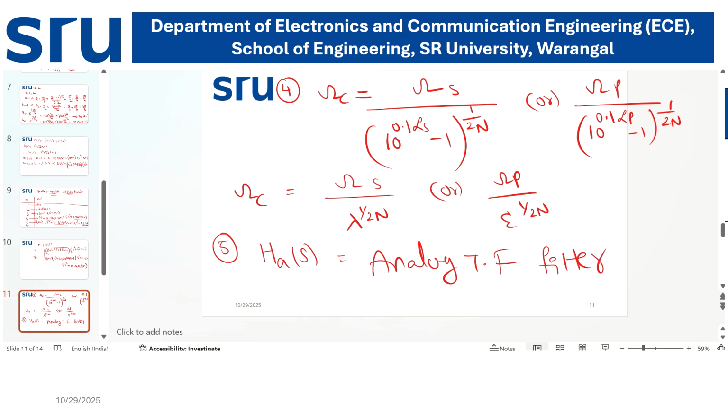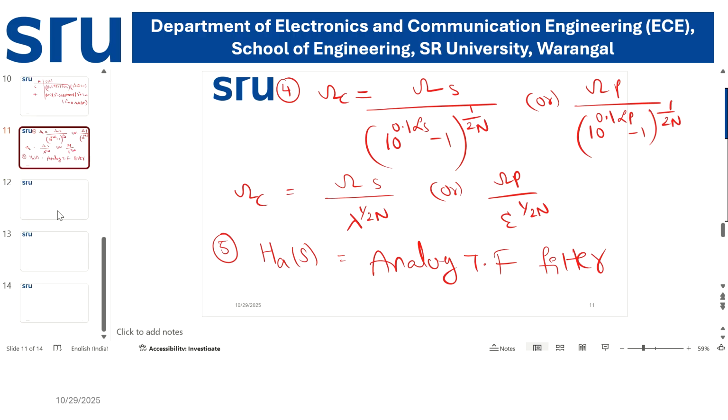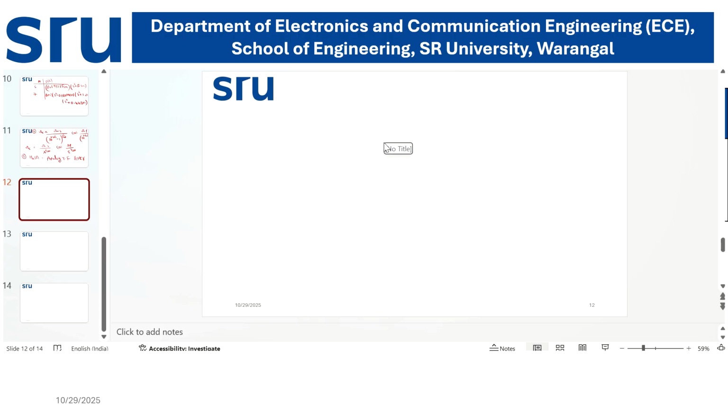To find this overall analog filter transfer function, from step number 3 we already got H of s, and from step number 4 we got the cutoff frequency. Remember the cutoff frequency, whether you are substituting the passband frequency and passband attenuation, or the stop band frequency and stop band attenuation, we have to consider the highest one.